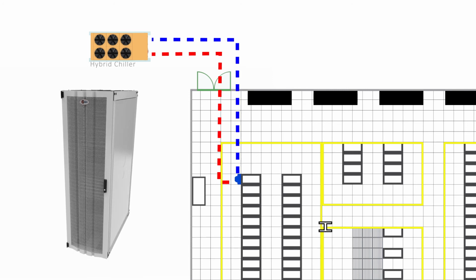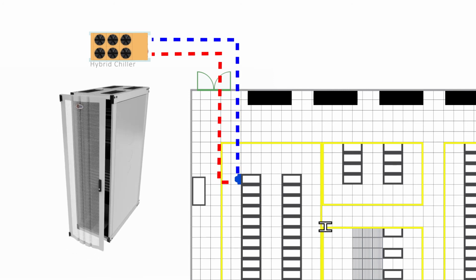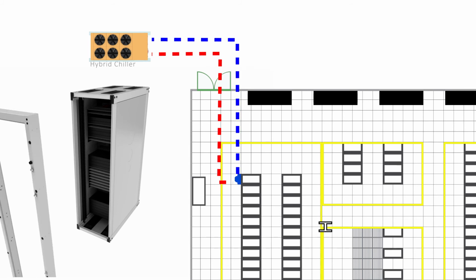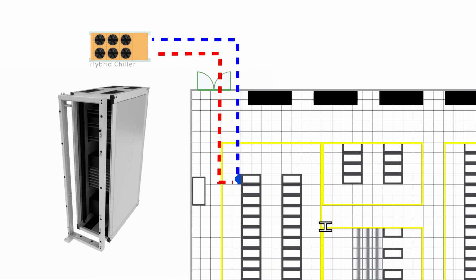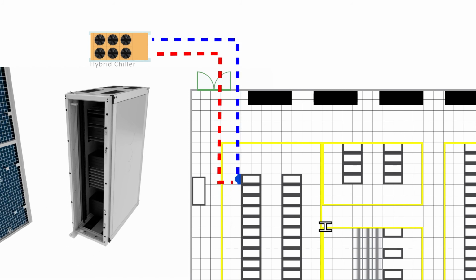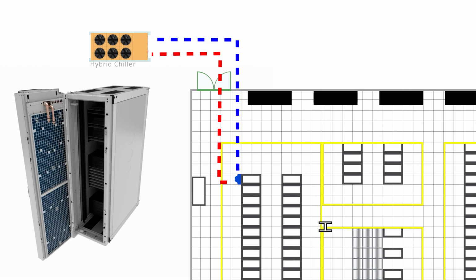Furthermore, there is less strain placed upon perimeter air conditioning in trying to attain a demand they were never intended to achieve. Arguably, rear door coolers are complementary to perimeter cooling, and because hotspots are removed in the process, there are far less engineering call-out tickets generated by customers, which is good news for facility managers and their customers. A win-win.